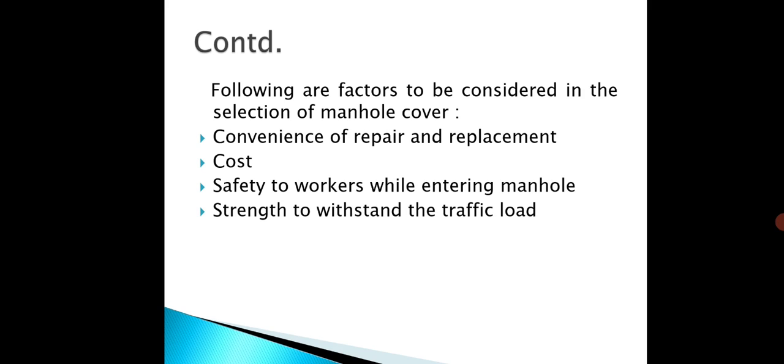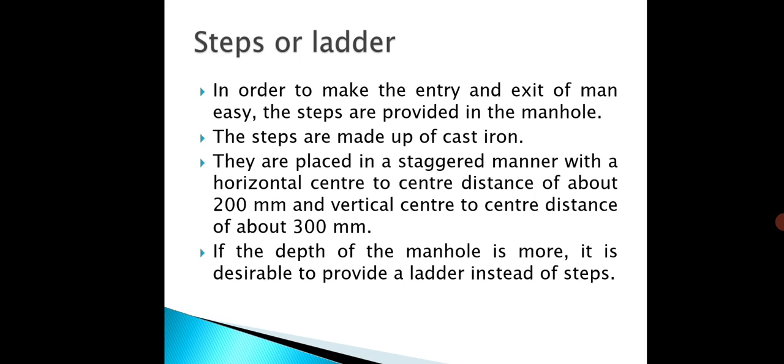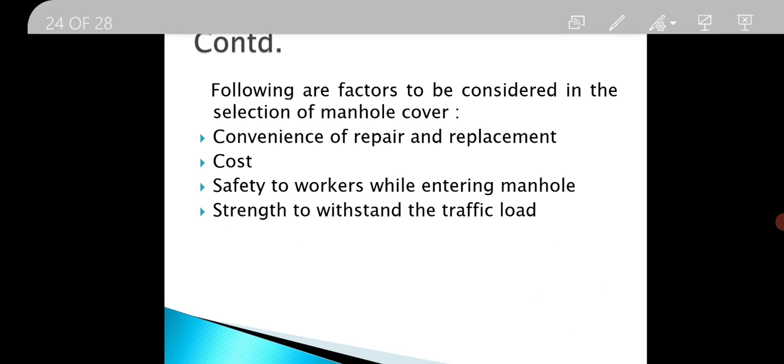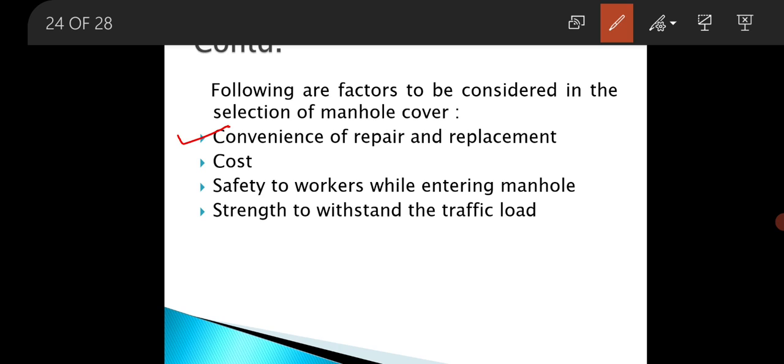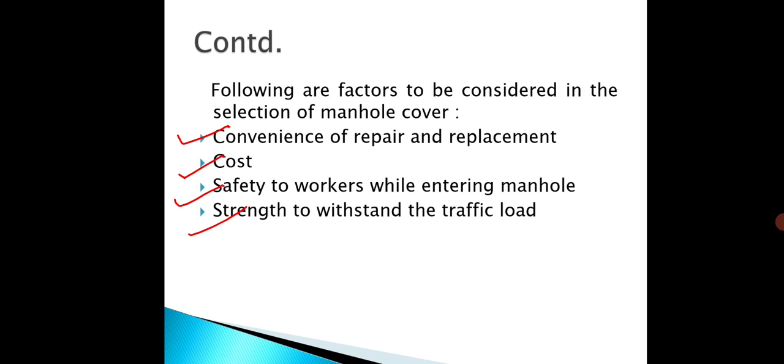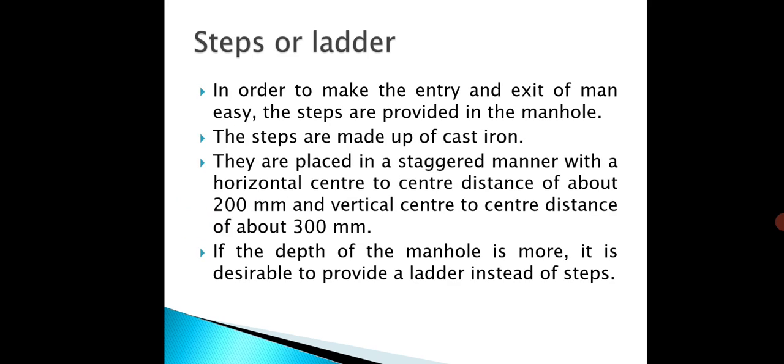So generally, while doing the selection of manhole cover, following factors are to be considered: it should be convenient to repair and replace, it should be cost effective, it will provide safety to workers while entering into the manhole, and it has strength to withstand the traffic load. These are the factors which we should consider while selecting the manhole cover.